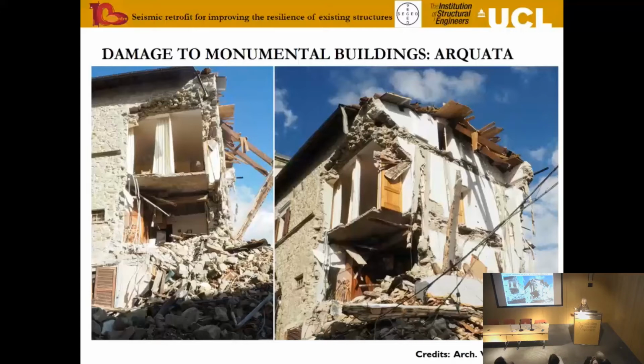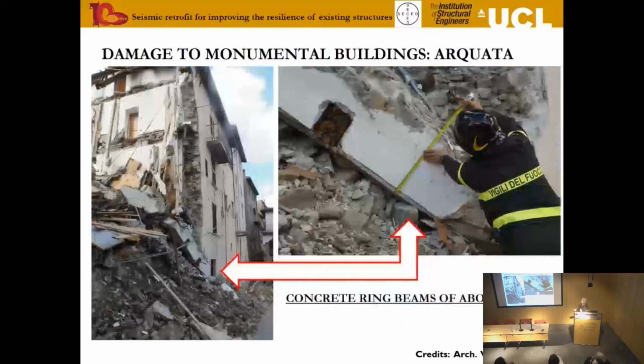This element here is the depth of the ring beam. As you will see from this photo, from the same side, the depth of the ring beam is more than 600 millimeters. Yes? And this was done so that you can increase the height under the roof and basically create another habitable space, which you didn't have before the retrofitting. So, very good investment.